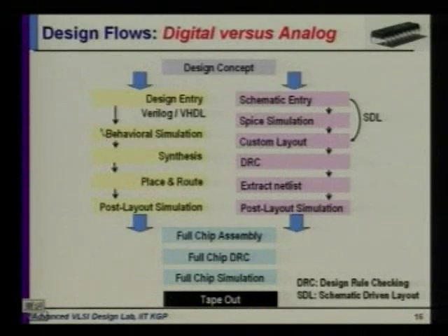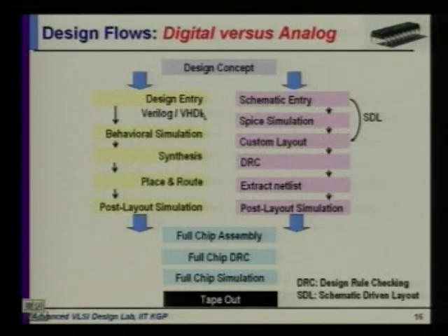Then once you are confident about the design, you go through what is called synthesis. So synthesis is actually taking the design specified in that language and translating it into your gate level design. Okay, now what is gate level design going to do? The initial thing had the logic, the intent of what you wanted to do, and that intent is implemented in terms of your gates, right? So there is a lot of logic optimization that will take place there. You want to minimize the number of gates in your circuit. There are a lot of tools which are going to do this synthesis for you, and you are going to learn to use those tools in this course.